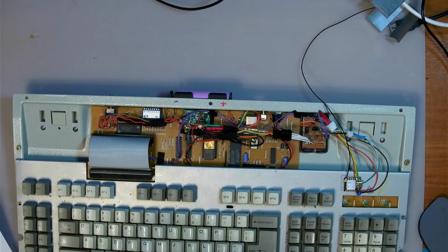I started to have a look. I thought, well, what could possibly be the cause of that? As soon as I plugged this board back in, it pulled it low, and if I unplugged it, it was high, and I could hit keys on the keyboard, and they showed the correct data. So obviously the keyboard was working, and it wasn't the PS2 signals. So I knew that then, and I thought, well, there is something going on. Either this board has gone bad, or there's something going on with the USB signals.